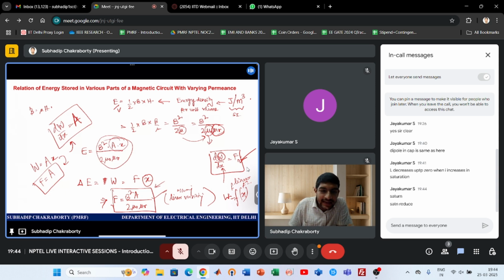And obviously with an air gap, electrically you are not doing anything, but magnetically you are reducing the chance of that flux actually saturating the core, because now your reluctance increases. So for that particular MMF, your inductor core will not enter into saturation. For the same MMF, now the reluctance is more. That is the whole purpose.